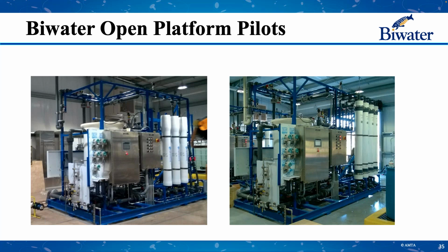So we have a multiple module skid that effectively has the same module in. We would run those in parallel. We'd have 2 of those units in parallel, so we can have 5 modules of one type on one skid, 5 modules of another type we want to compare on the other skid, and those systems will operate in parallel on the same raw water source at the same time, feeding downstream to something like an 8-inch RO membrane system.